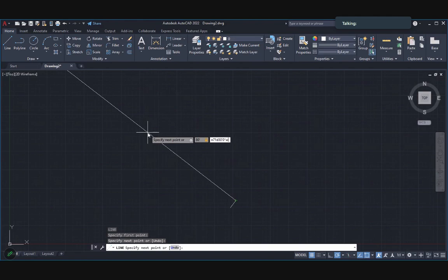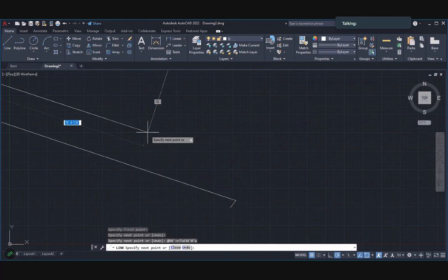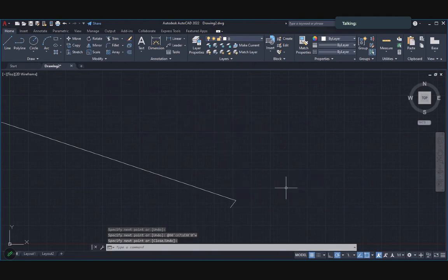Okay, so that's how to put in north 71 degrees 30 minutes 0 seconds west, and I simply will press enter. And then at this point what I can do is stop the line and then press enter on my keyboard. It'll stop the line, and here's where I made a mistake. I click, I'm going to just delete that. Delete. Nope. I'm using two keyboards here. I'm getting confused now.